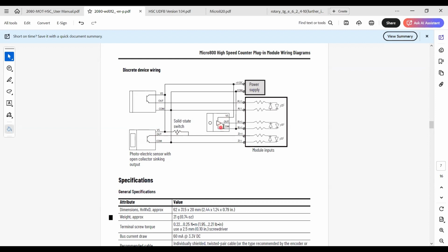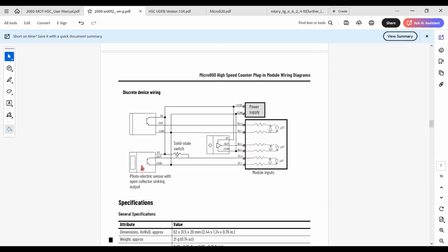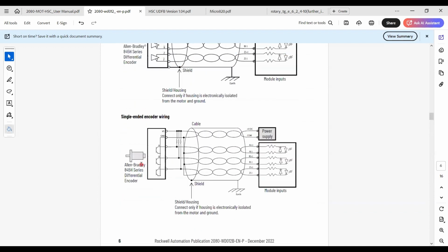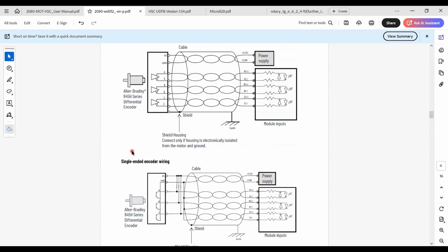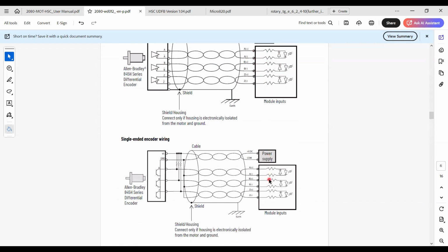This is another configuration like an op amp. You have VS supply in, output, and COM. So the output is high when it is true. Then it will drive the encoder with logic high. When this is 0, the output voltage becomes 0, and this voltage becomes 0, and the encoder signal is 0. So there are different types of encoder outputs. You have to refer to the manufacturer's specification of the encoder itself, and then you have to do the wiring of your high speed counter module.